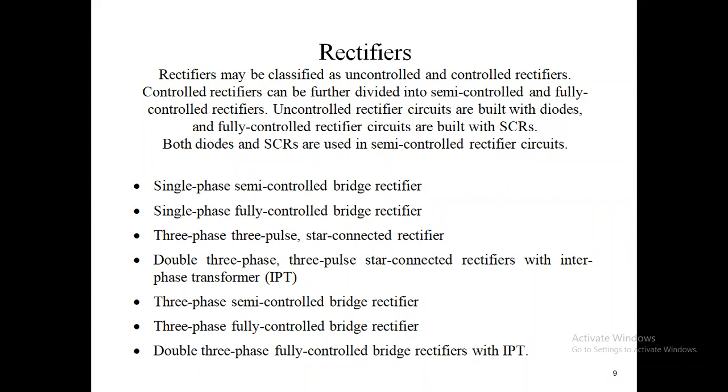Then after that you will be going to three phase conversion. If you have three phase AC supply and you want to convert it into DC, then you have three phase rectifiers, like the three phase half wave rectifier and the three phase full wave rectifier. On the basis of the use of devices, there will be two kinds of rectifier in three phase also: one is the half wave and another is the full wave. There will also be semi-controlled and fully controlled ones on the basis of the use of those devices. So this is what we will be going through in the rectifier.